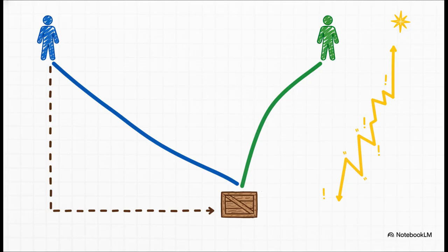It requires a really standardized approach to be truly effective. To make sure your diagram tells a clear story rather than just becoming a chaotic sketch, you must strictly follow these notation conventions. First off, always use a unique color for each person or part you're tracking. Second, number every single leg of the path in the actual sequence it occurred. Third, make sure you distinguish an operator's travel from material travel by using different line styles, like solid versus dashed lines, for example. And finally, map out those rare exception paths differently so you don't accidentally overstate how often an unusual trip actually happens.